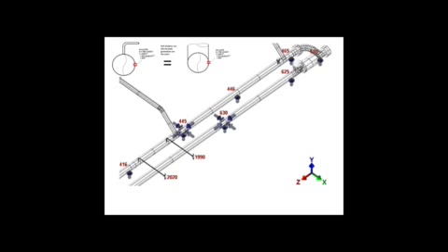It could potentially overstress the main header pipe in a completely artificial way due to the SIF from the pipe that's attached. In addition, there's very little flexibility in that small piping branch, so when this large horizontal run moves the large run header, we're going to crush that small pipe. In those cases, it's very important to evaluate the flexibilities and the SIFs where the small pipe is attached to the big pipe, so that we recognize where we've got real stress problems and artificial ones.